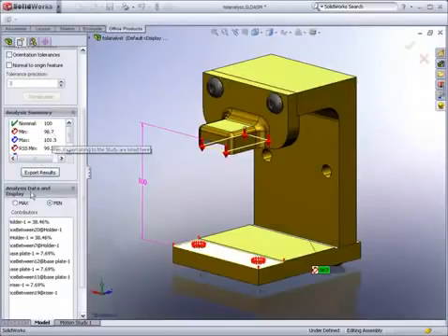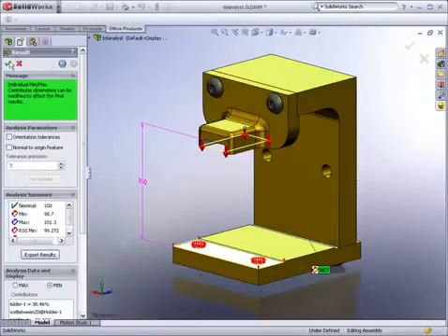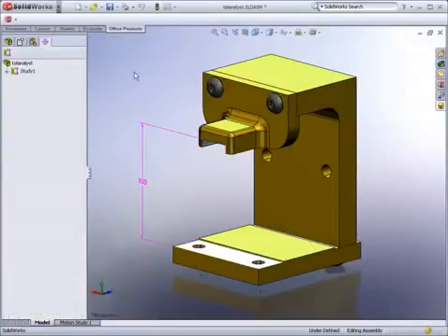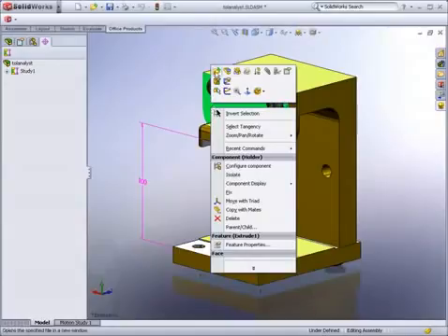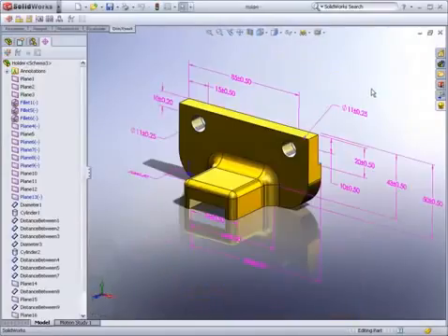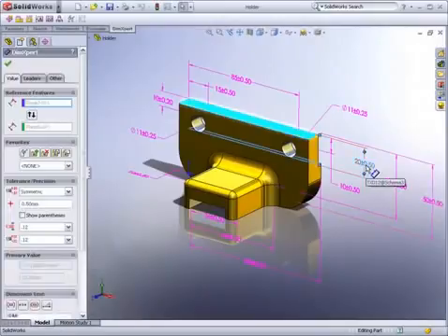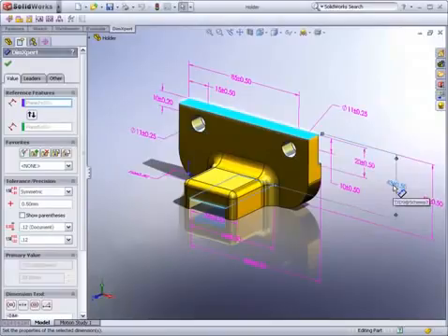We can now see that the two new major contributors are in the same part. So let's open that part and examine the dimensioning scheme. Here you can see that this dimension controls the top of the part to the small shoulder, and this dimension controls the top of the part to the top face of the slot. What we are really doing with this dimension scheme is building in a double tolerance from the top face of the slot to the shoulder.